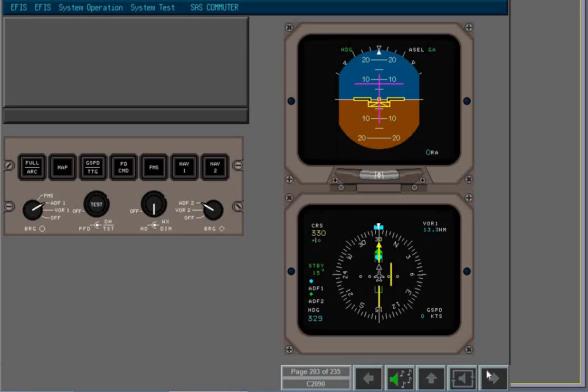The electronic flight instrument system test is achieved by pressing the test button on the decision height knob. For the test, the autopilot command push button should be set to the side to be tested. Normally, the test patterns are displayed for as long as the test button is held pressed. For instructional purposes, the test patterns will remain on the DUs.